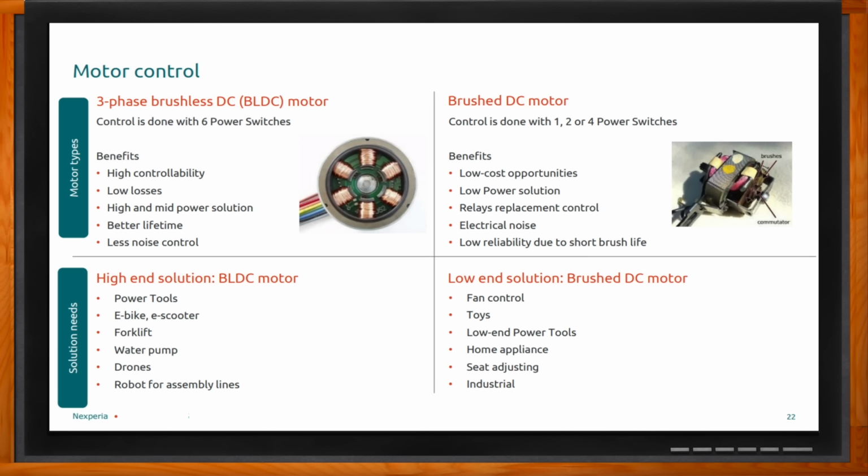The good thing about brushed motors is they're extremely inexpensive and they're easy to control because all you need to do is vary the voltage you're applying from, let's say, 0, full stop, to, let's say, 12 volts or 48 volts, depending on what the motor is. But the main issue with that, the brushes will wear out, and that gives increased maintenance intervals and also increased noise, also the possibility of windings being shorted because there are too many sparks flying internally. So there are a lot of drawbacks to brushed motors, but there are some good things. There's always a silver lining somewhere.